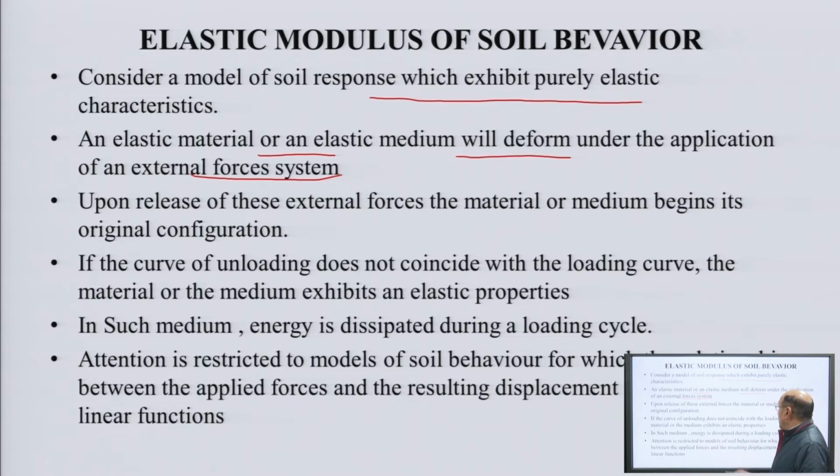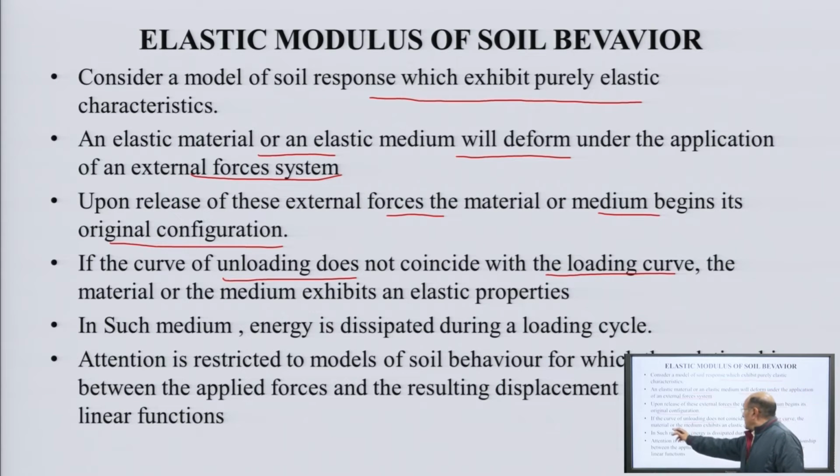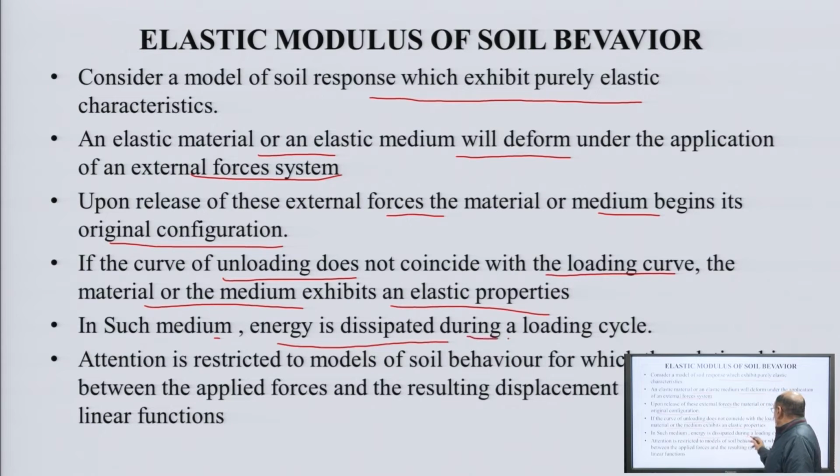Upon release of external forces, the material or media regains its original configuration, means tries to attain its original shape. If the curve of unloading does not coincide with the loading curve, the material or medium exhibits an inelastic property. In such media, energy is dissipated during the loading cycle.